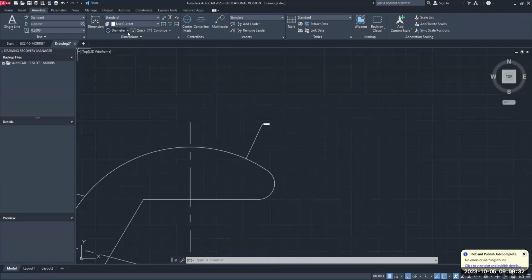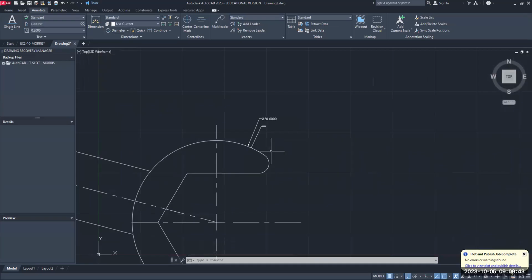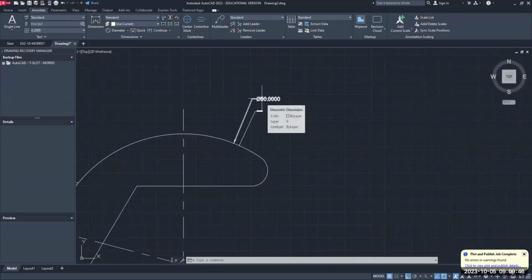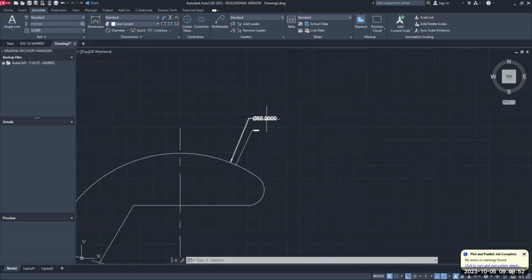I'm going to go back to this diameter. Look, I've got one more thing I need to change here, though. In actuality, I think that's still too small. So we'll make it 4 times this size. I'm going to erase this one. That's good practice. Type in DIMTXT, and let's just make it 1.25 or something. Make it 1.25. Enter. Type in dim arrow size. Make it 1.25.